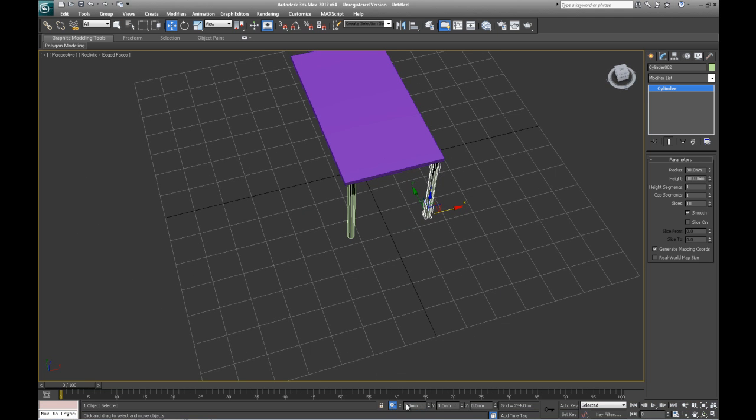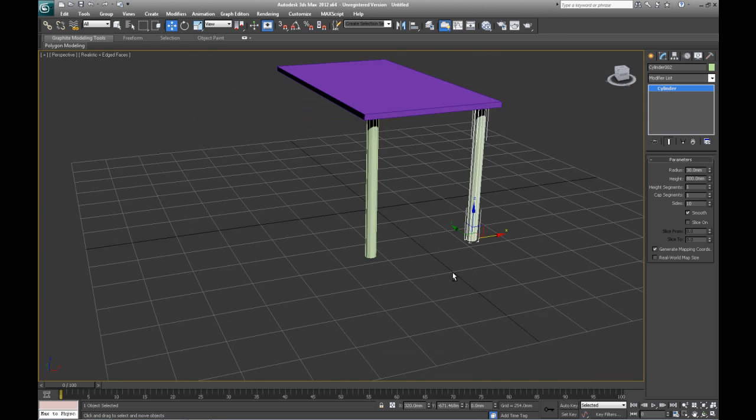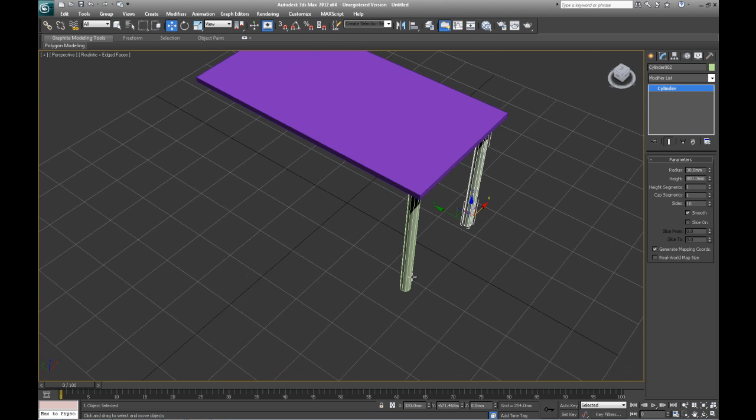So if I make it relative to its own things, minus 50. You can see now that that's off. And okay, it'll move into position and bring it back to the world view, or the world reference points. And now if I select both of these objects, let me get the selection tool, and control select both of those, and now hold down Shift and drag this out.